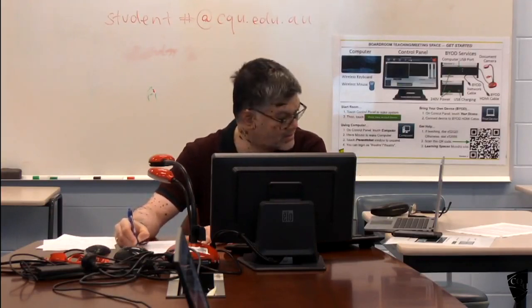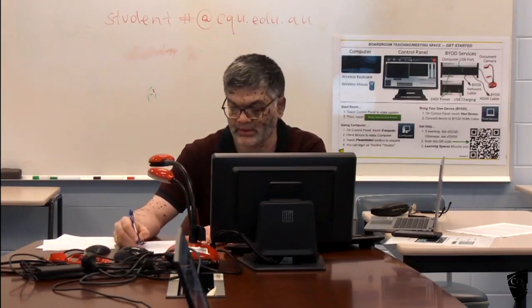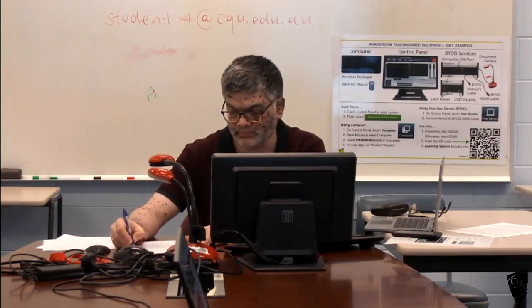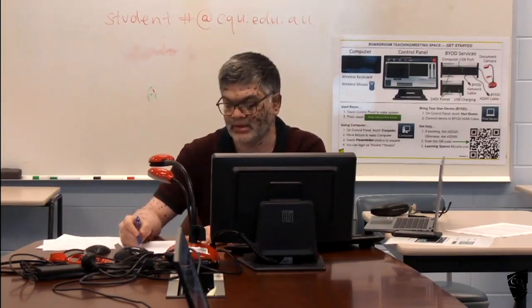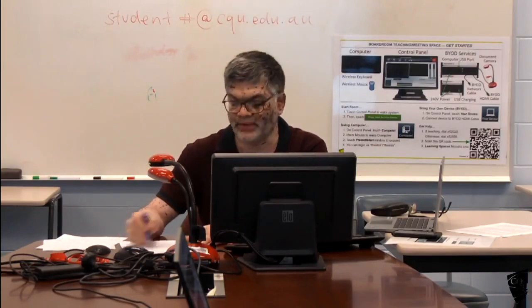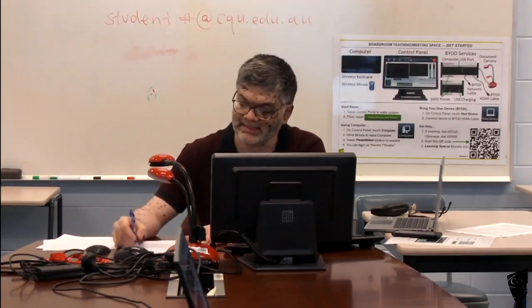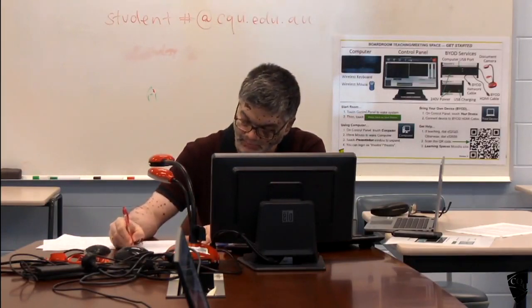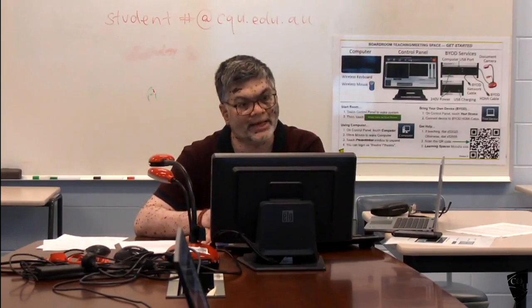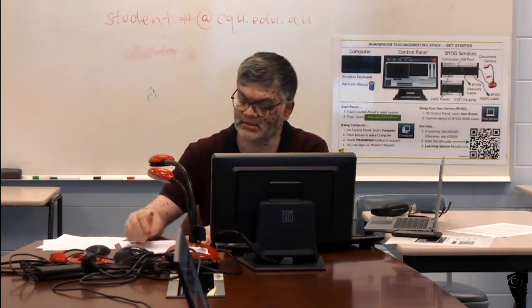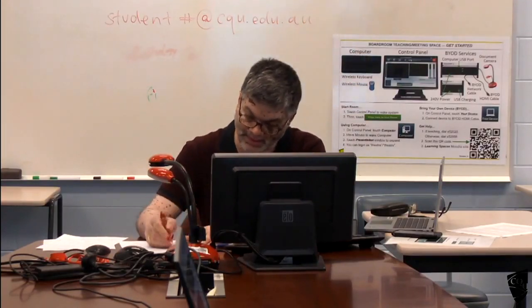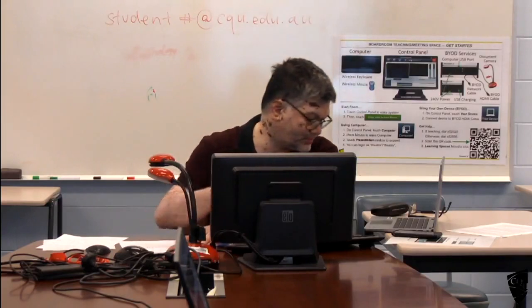point 621, this much is the factor for the column strip. Column strip will take 60 to 100% of the moment here. Okay, so since it is a range, normally we use the average value, which is 0.8. Okay, 80% of the moment of the design strip will go to here. So 80%, how much? 80% of 750.